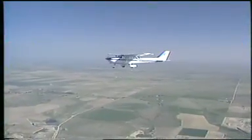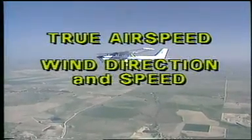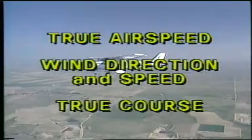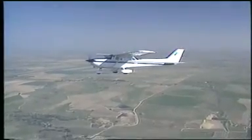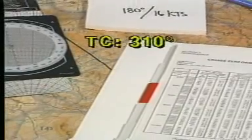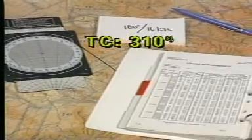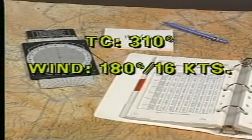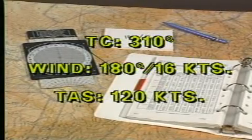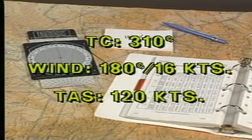To determine how wind affects your airplane, you will need to know true airspeed, wind direction and speed, and true course, which is your intended flight path as measured from the true North Pole. The method for determining true course will be explained in the next section. Suppose that you've determined your true course to be 310 degrees. The predicted wind at your altitude is forecast to be 180 degrees at 16 knots, and your true airspeed is 120 knots. What heading will you have to fly to maintain your desired course, and what effect will the wind have on your ground speed?